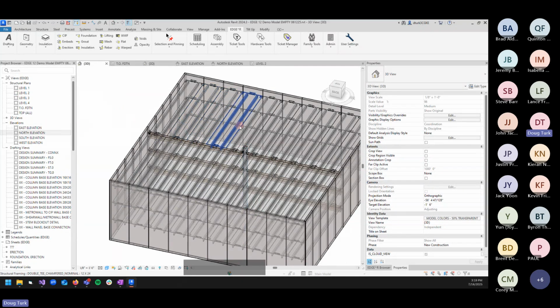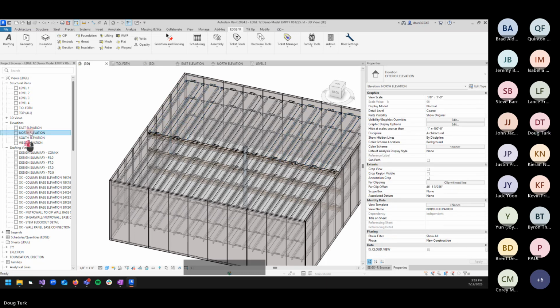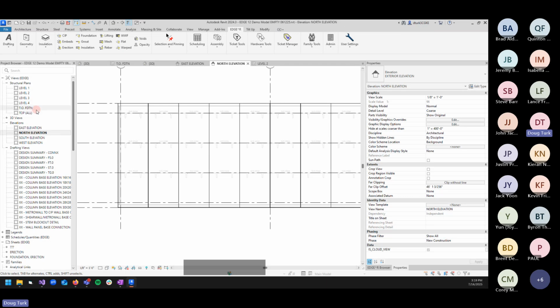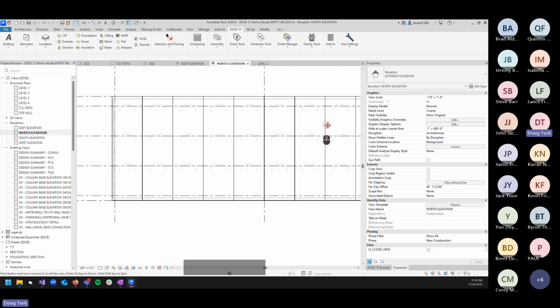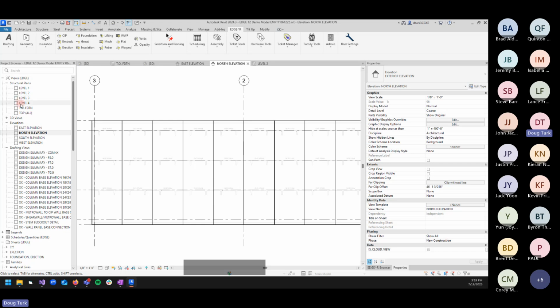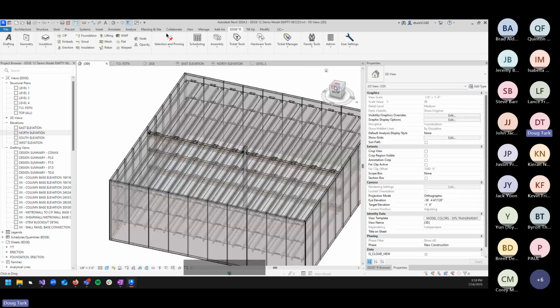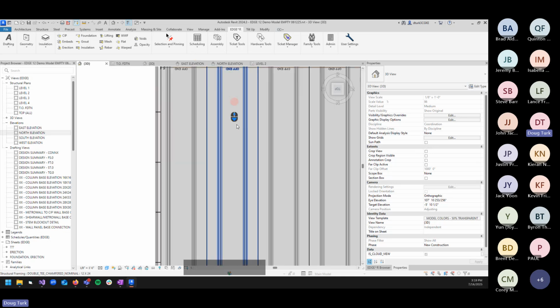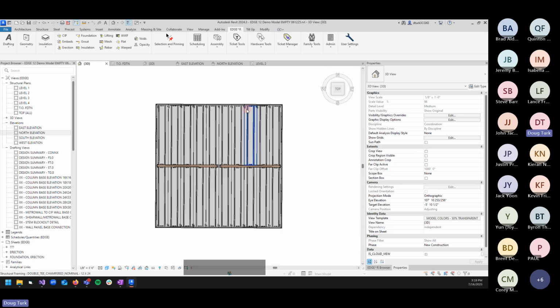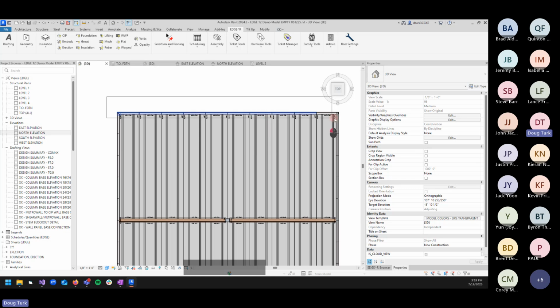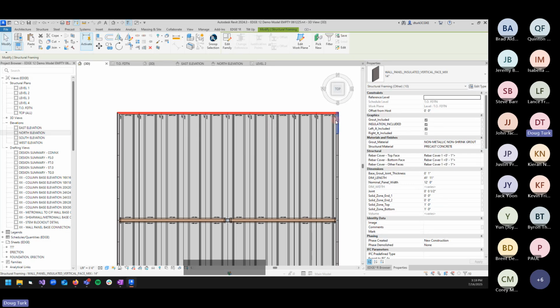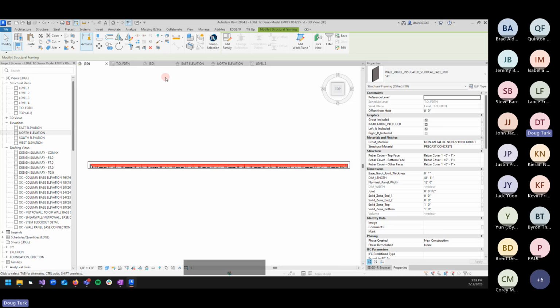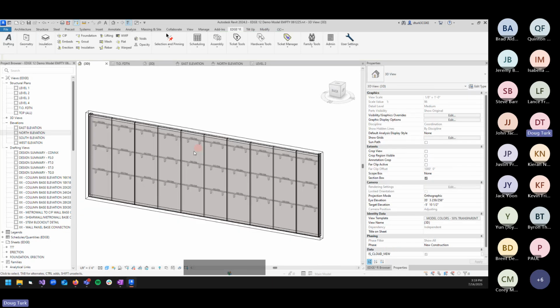Now, what I want to show next is some of the different things that you can do as far as placing geometry modifications like voids and add-ons, as well as a small dip into some hardware and connections. So what we're going to do is go into our 3D view, and we're actually going to pick, let's see, where's our corner that has the good adjustment? Let's do the north side here. We're going to select all of these walls, and we're going to use the section box tool so that we can see just those walls, so we can focus on what we're working on.